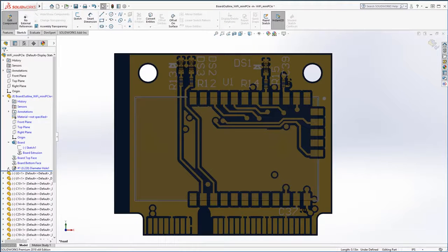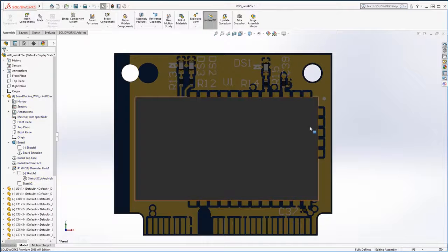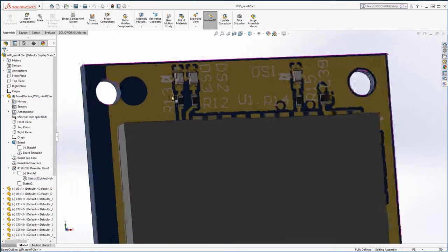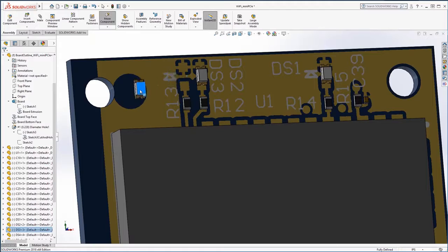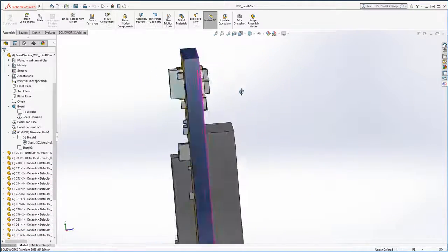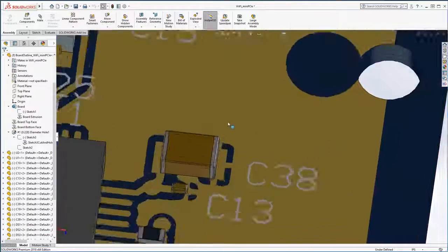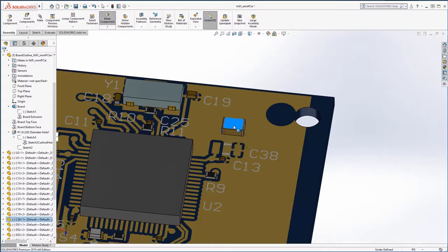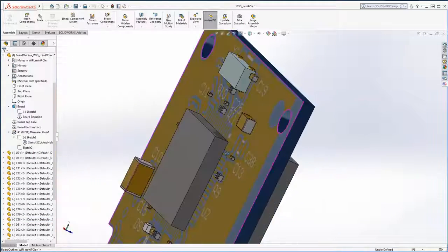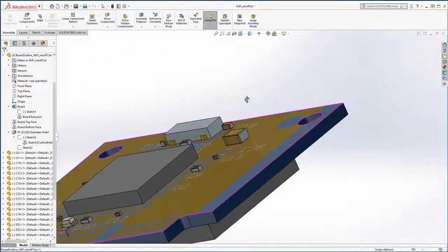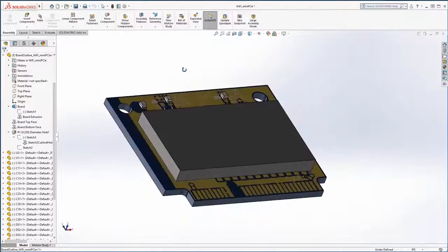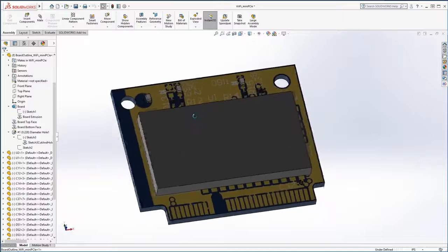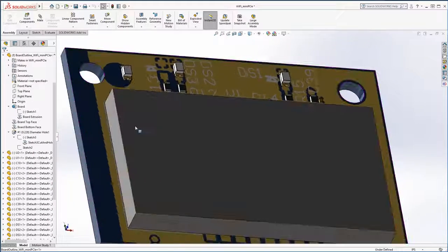Then I'm going to want to edit some holes. Here I'm taking one of the holes and slightly moving it towards the side. Okay. These are simple adjustments on the board, but let's say I also want to move this component here. As you can see, I cannot detach a component from the surface of the board. I can only move it along that plane. Right now it has mating applied to it, which makes it attached to the surface of the board, which means that the system doesn't let me do any irrelevant actions with it.